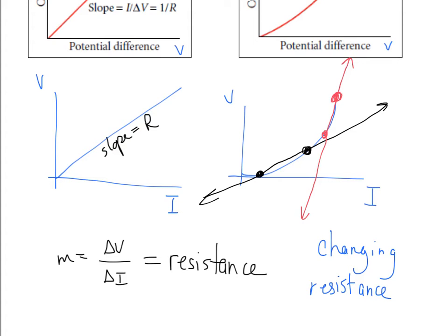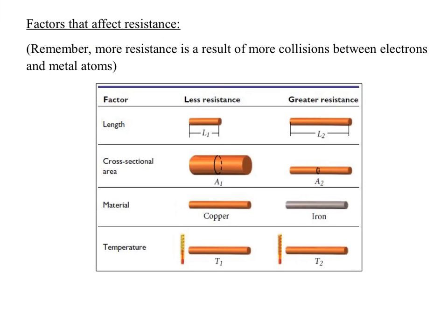All right, so traditionally, you're going to use materials that are ohmic because you want a predictable resistance. You don't want the resistance of something to change just because there's more voltage suddenly. If the voltage and the current both go up, the resistance should still remain the same. It should not change at all. So usually, we're going to see applications where things are ohmic materials.